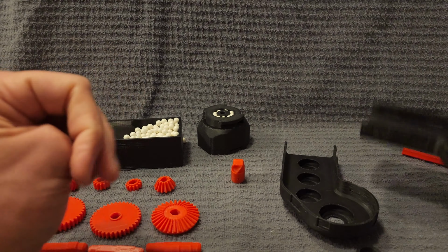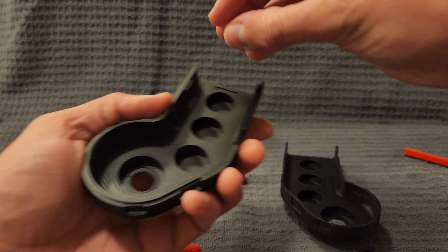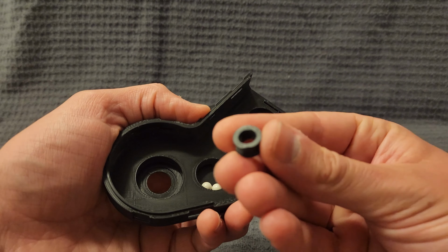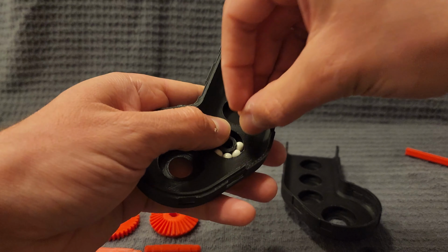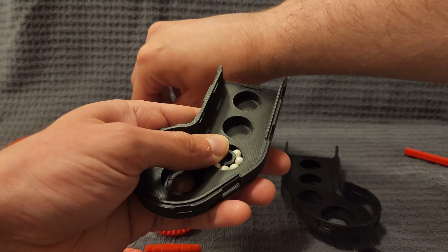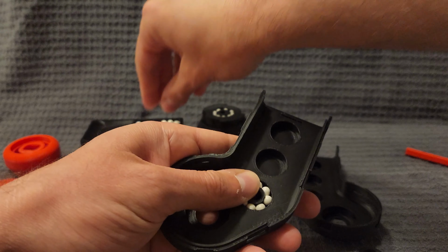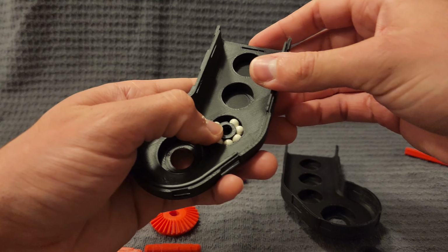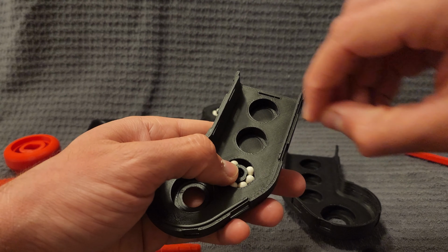An important thing when you're slicing and printing the parts with BB tracks for the bearings is to use random seams. If the seams on your print are all aligned, it's going to create a bump in the print, and that bump is going to provide intermittent resistance in the bearing rotation, which is something you really don't want. My previous print on the Supreme launcher had those seams, and it performed a lot less smoothly on the gearbox rotation. So you've really got to be careful with that.